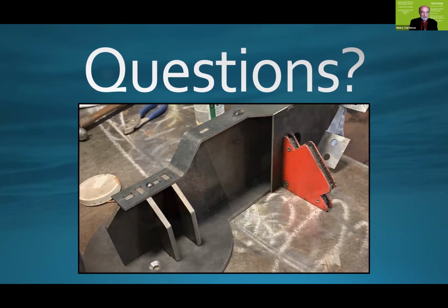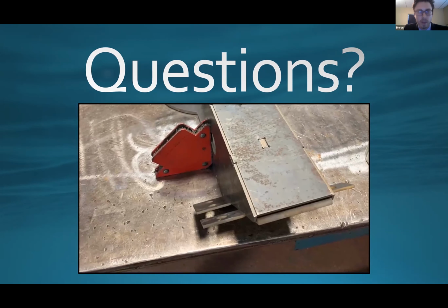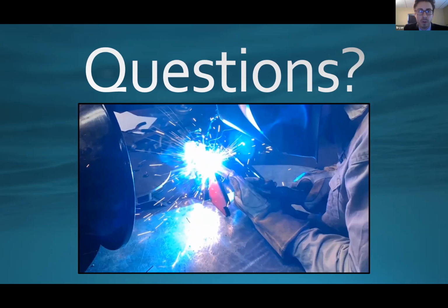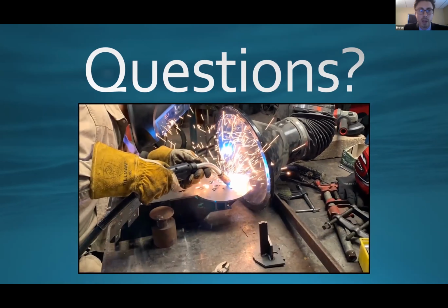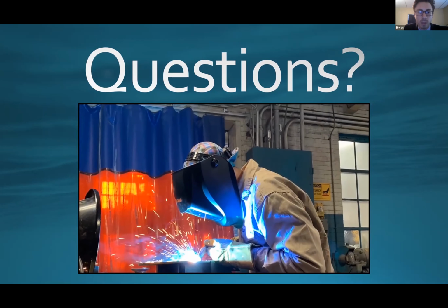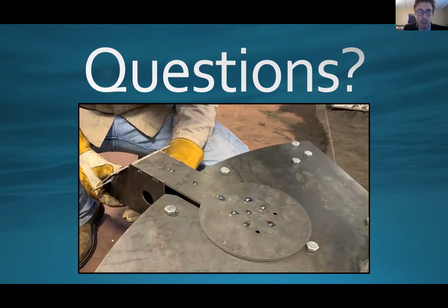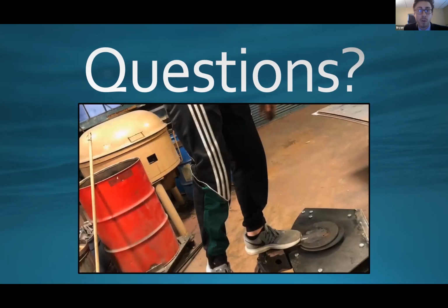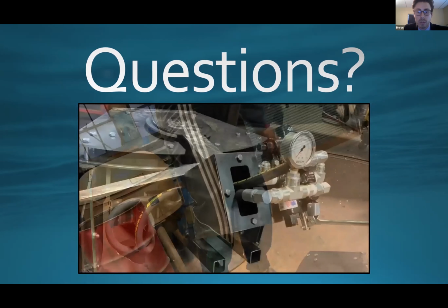So something that we learned during this project was about the hydraulic systems on board of an ROV. And that was kind of our first major concern because when you get that deep, you've got a lot of hydrostatic pressure. What's really neat is there's systems on board the ROV to compensate for the pressure outside. And so that was one thing we learned pretty quick that simplified this. We didn't have to overbuild our hydraulic system in order to meet those pressures.